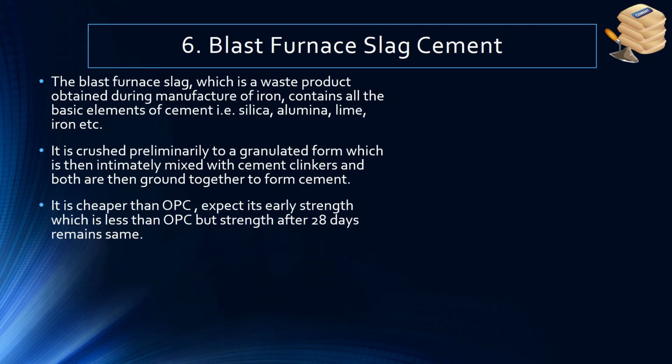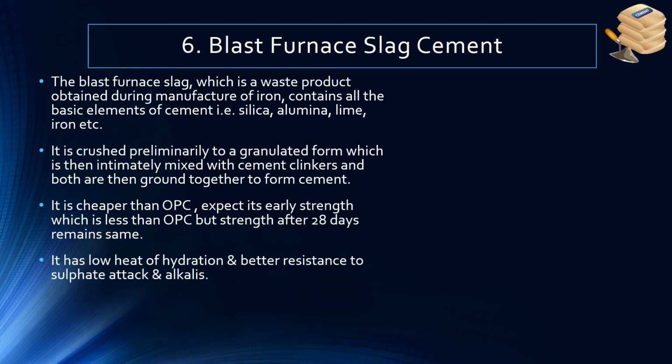It is cheaper than OPC, except its early strength, which is less than OPC, but strength up to 28 days remains same. It has a low heat of hydration and better resistance to sulfate attack and alkalis. Because blast furnace slag has sulfur absorption capacity, it has a better resistance to sulfur attack.